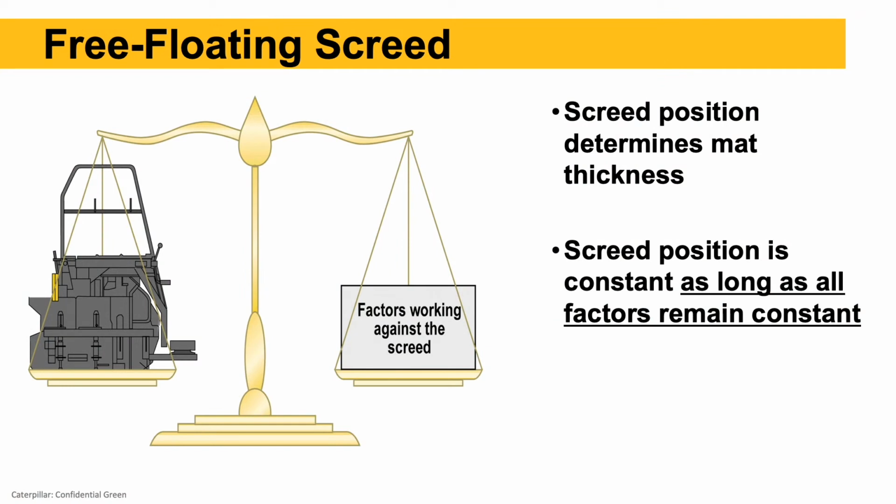So the screed's free floating. Again, screed position is going to determine your mat thickness. So where that screed is, again, it's just floating on the mix. So the position is going to stay constant, or your thickness will stay constant, as long as all those forces or factors acting on that screed remain constant.